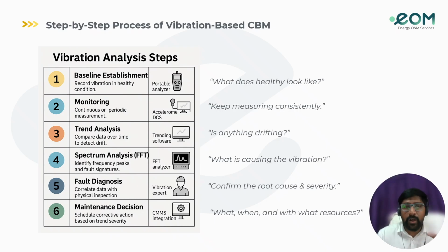It converts all these diagnostics to a preventive work order in the CMMS, choosing a corrective action, for a balancing or alignment or bearing change or structural regrouting. So this is the step-by-step procedure for vibration analysis in condition-based maintenance.